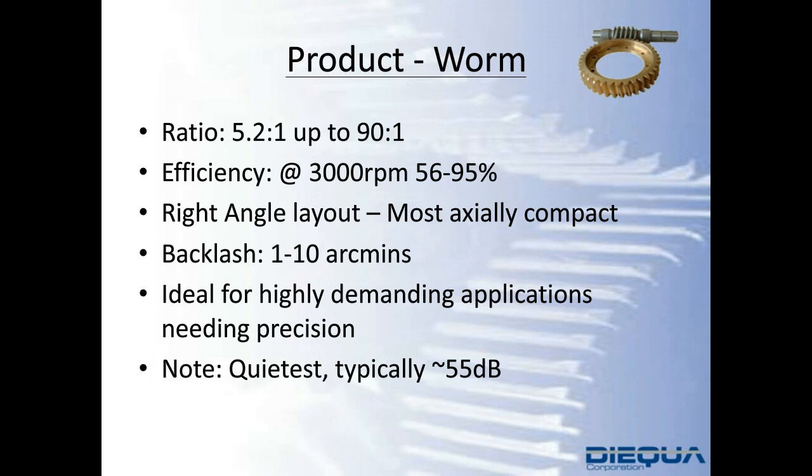This is evident in ratios that are 45:1 and greater, as well as gearboxes that are smaller. So just like efficiency, size and speed are influential; in this case for self-locking, it's the size of the gearbox and the gear ratio that dictate the lead angle to then warrant whether it's going to self-lock or not.